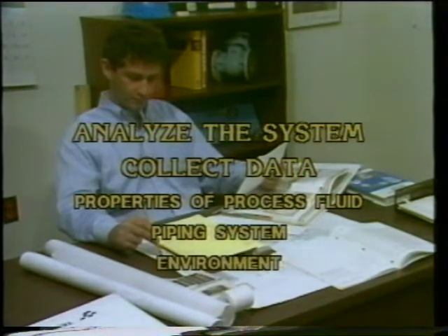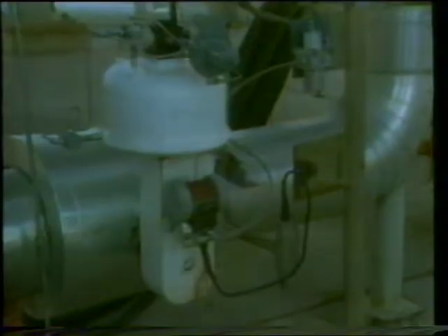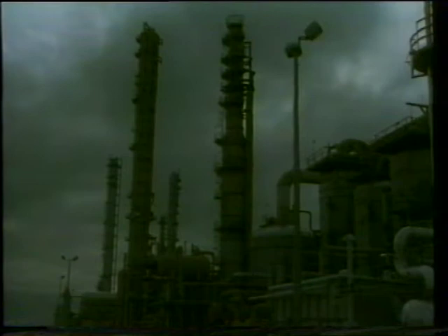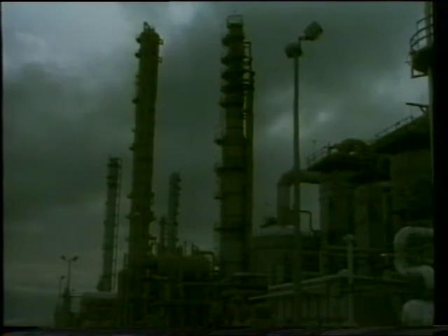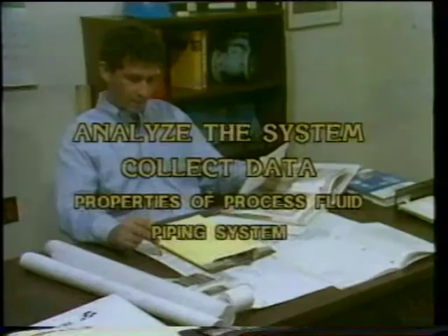The environment where the valve will be installed can also have an impact on valve selection. As you may recall, the classification of the area for electrical hazards is one important factor when making a selection. Other factors include climatic conditions, such as temperature extremes, atmospheric contamination, such as corrosive dusts and vapors, the seismic zone classification, and any unusual plant procedures such as washdown or decontamination.